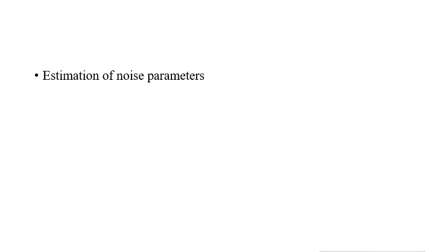Speaking of the estimation of noise parameters: when we speak of periodic noise, just now I told you that we can estimate the parameters or the frequencies present just by inspection of the Fourier spectrum of the image. You saw that the periodic noise will produce some kind of frequency spikes, and we can observe that using some visual analysis. So it is important to infer the periodicity of the noise components from the image. But this is not always the case. In simplistic cases, this is possible. Sometimes you need some automated analysis, in situations where it is not possible to arrive at the parameters from visual inspection.